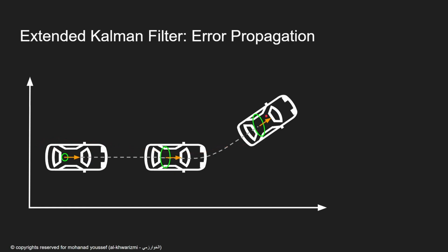The output from this prediction step will be that, given the inputs that we measure from the odometry wheel sensors and the inertial measurement units like the gyroscope and accelerometer, we can have these kinds of updates, so the trajectory of the vehicle along with the uncertainty at each position. Since here we only talked about the prediction step, there is no update yet.